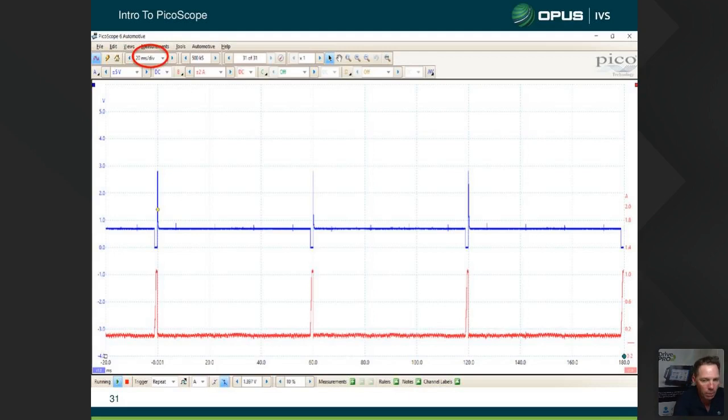If you're measuring live sensors, so real-time sensors, like an airflow sensor or an oxygen sensor, something that gives back information in real time, or even a throttle position sensor, what you want is about 5 seconds per division. So we'll have 1 1000, 2 1000, 3 1000, 4 1000, 5 1000. So 5 seconds across there. And that's fantastic for oxygen sensors or anything like an airflow meter. So we crank the throttle and we want to see the airflow increase and then decrease as we hit rev limiter. 5 seconds is a great real-time measurement.